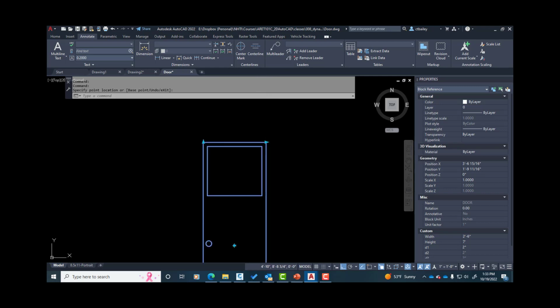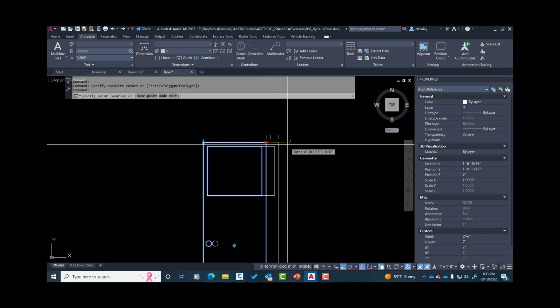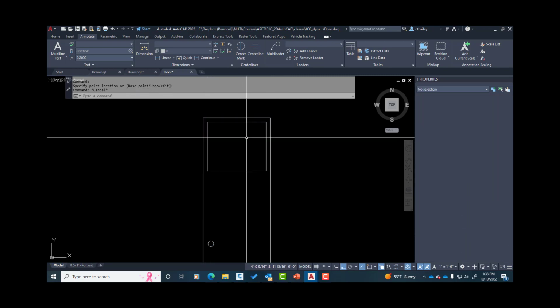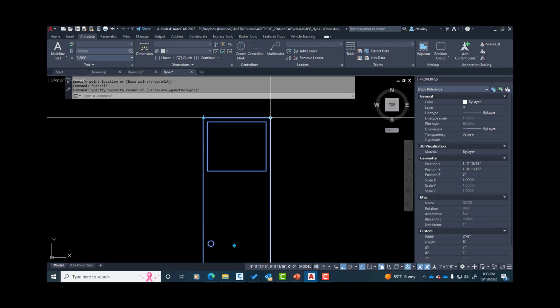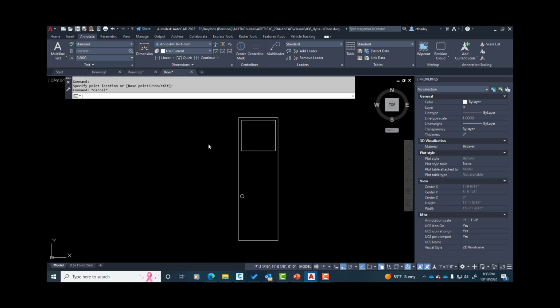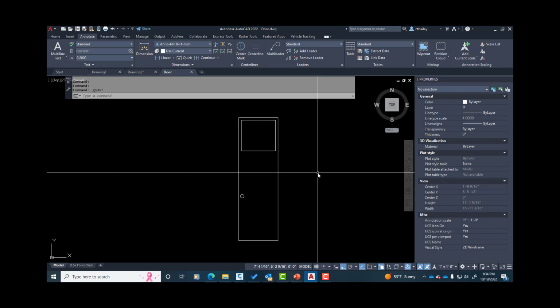that now we have a door that kind of pulls to 3 different sizes and 3 different heights, and the window goes with it. Okay. So using a good combination of dynamic blocks, actions, and also geometric constraints and some dimensional constraints, we can get some very, very cool solutions for some dynamic blocks. Alright, so we'll go ahead and hit save on that, and that will be part of the assignment for lab number 8.